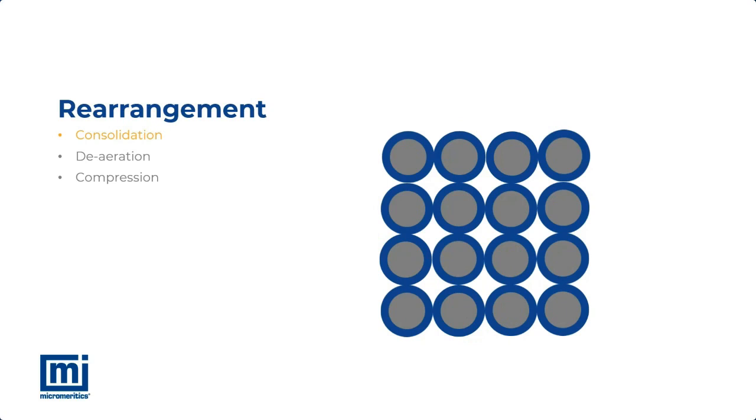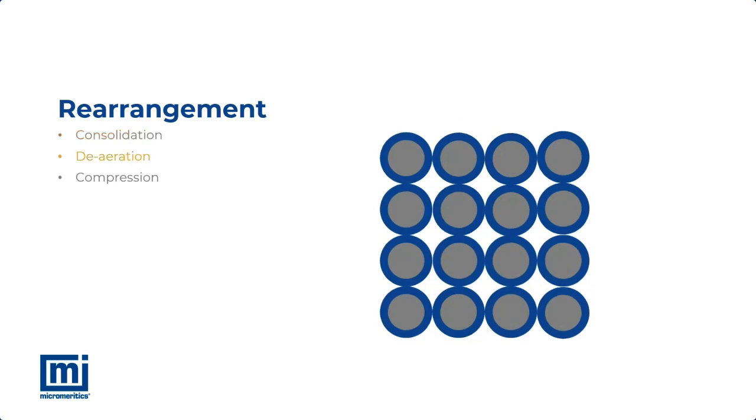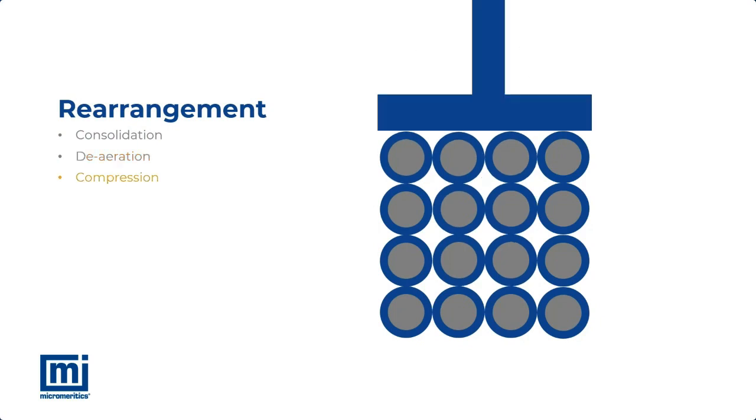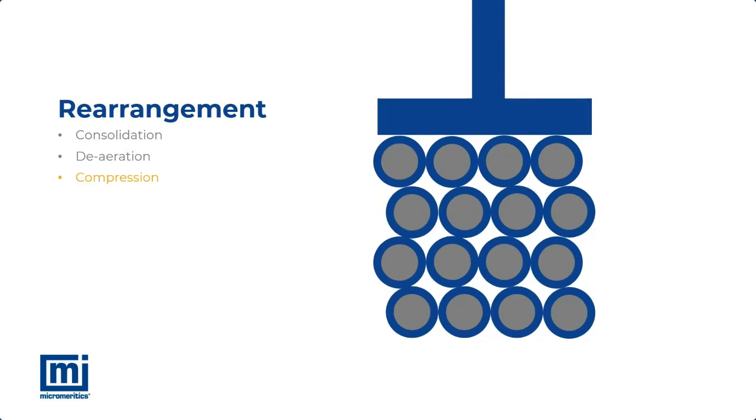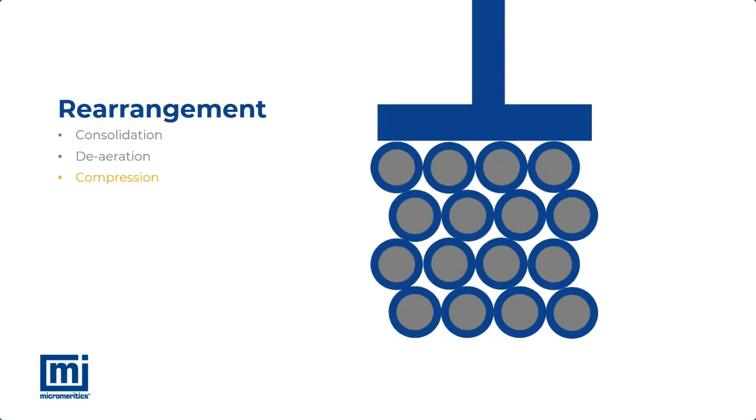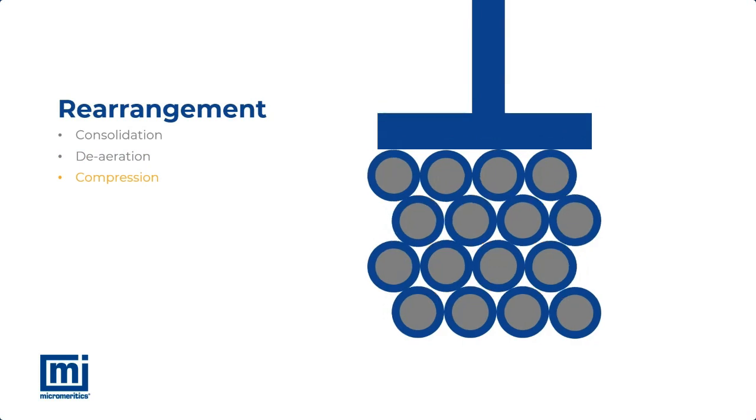Consolidation can occur through vibrations allowing the particles to slip into a more organized state, which is accompanied by deaeration of the powder as space taken up by air is replaced by particles. And we may observe active compression of the powder by some external force. This could be applied deliberately or, more often than not, simply by the mass of powder acting upon the layers of powder below, or containers of powder being stacked on top of each other.